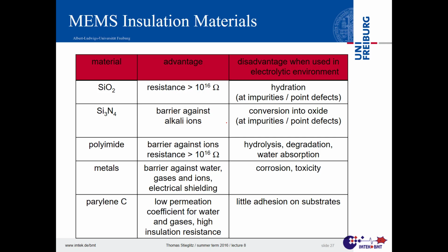And in many cases, if we look up the materials, we should look up the methods to work with the materials in parallel. So if I would say silicon dioxide, I would have a single crystal orientation in mind that is different from something where I have silicon and oxide, but it's a wild mixture of materials and not in a crystalline phase. So we always have to check a little bit, is it crystalline, is it amorphous, do we have other agents in there from the manufacturing process.